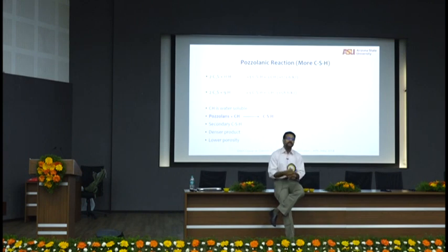That is purely from the point of view that you will get the filling of particles in a volume fairly nicely. The advantage also is that with fly ash, if the fly ash is really spherical, you can reduce the amount of water. Therefore, the effective particle packing will even be better.